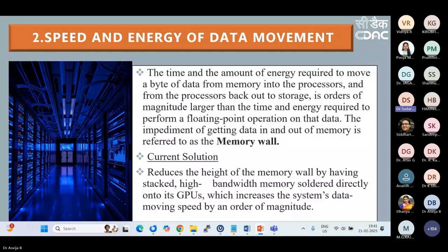Another benefit, not openly or directly understood, is security. Today, any cyber security person does side channel analysis. They try to work out, from the side channel or just the heat pattern that is generated, what kind of data is moving. So minimizing data movement lets you operate your compute in a stealth mode, so to say, which improves your cyber security posture. It is an extremely important but not openly discussed benefit of reducing data movement. Probably we are not keeping an eye on it, or it is not the first priority when we design a solution. But if somebody is looking at something that really makes a difference, these are the aspects we need to look at. So data movement has to be minimized, and in-memory computing is gaining popularity, and that is the takeaway from this slide.